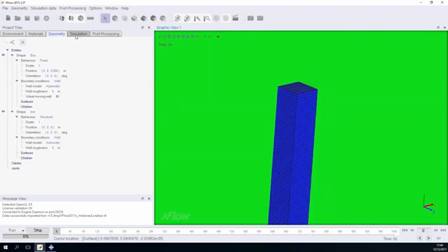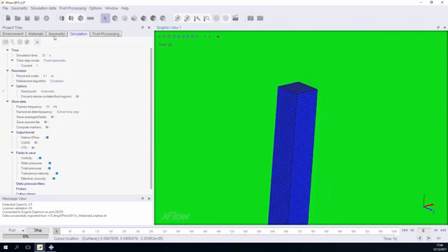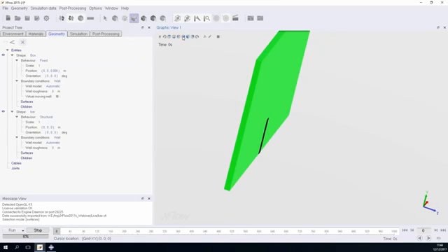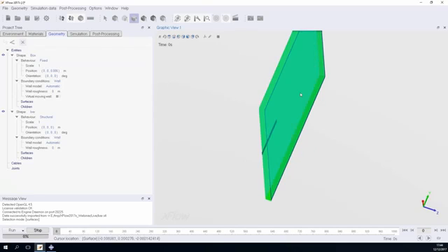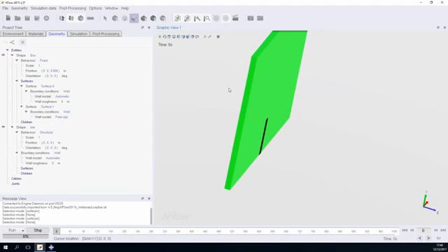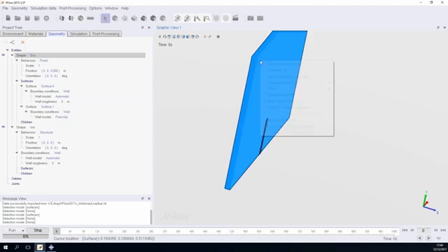Let me do a few other settings. If I set a few boundary conditions, on the sides I'm actually going to set free slip boundary conditions, because I don't want any friction on the sides of my domain. So that is going to be, instead of an automatic, a free slip condition. Perfect.